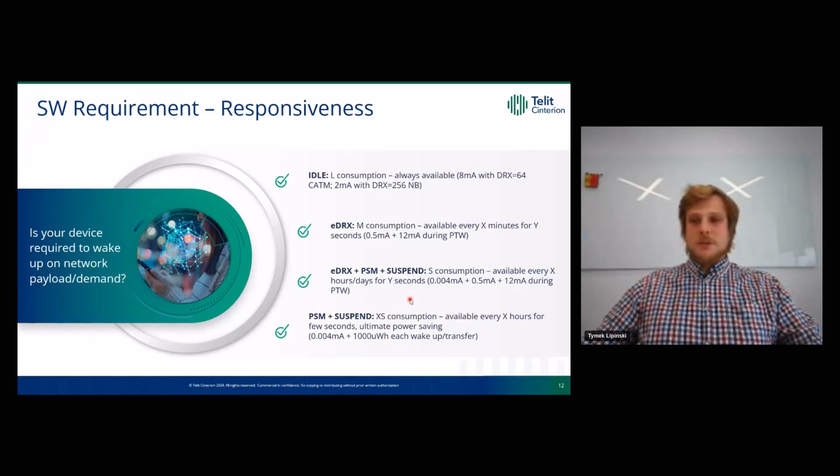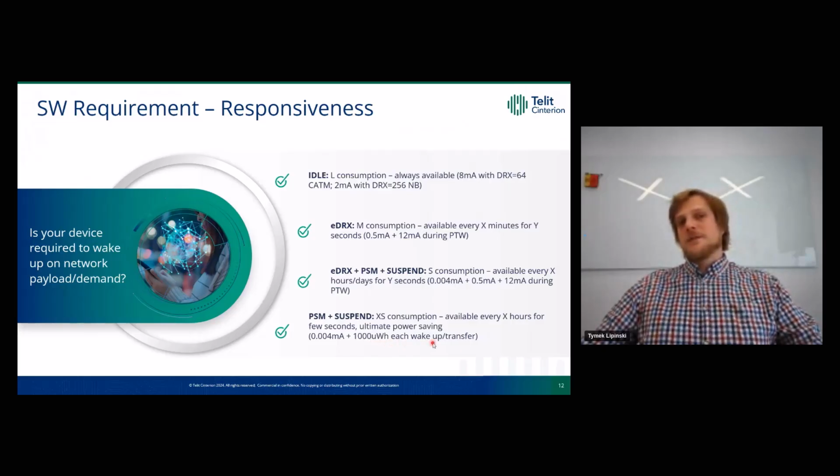It's super small consumption, very similar to the previous one, but we skip the 0.5 milliamp waiting period, and it's simply below 4 microamps while we are sleeping, and roughly 1000 microwatt hour for each wake up and data transfer and download.